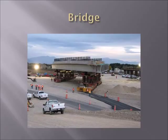ABC, or Fast Track Bridge Design, is another design tool that's gained popularity across the country. The use of structural lightweight concrete on the bridge decks has also gained in popularity. Not only does the reduction of dead load from the deck help in the ease of move of the bridge section, but in some cases a full line of girders have been able to be removed due to the additional width available because of that reduction in dead load.